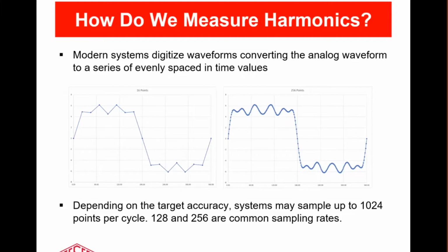So here on the left side is a waveform, and I only sampled it 16 times per cycle. And you can see sort of what it looks like, but if I was trying to do an accurate measurement of it so I could calculate, for example, the power in it, that's not really good enough.